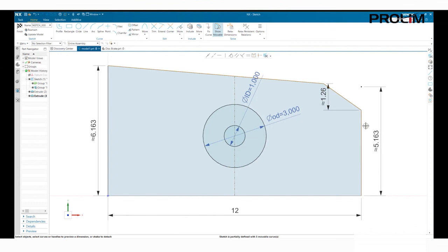So the first thing I want to do is show what's called break and shake, or shake and break. You go ahead and click your line, you go ahead and shake your mouse, and you notice how it breaks from the sketch now. It goes in and actually breaks any of my constraints that I have. It's a nice little way that you can actually go in there and break your constraints.